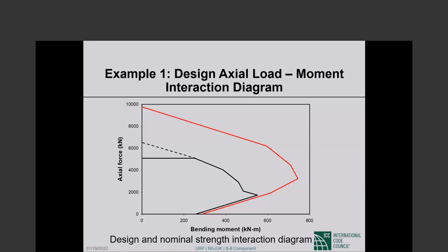What I want to say is that it is seldom that a spiral is compared with comparable circular ties. If you have a spiral with a pitch of 3 inches, I doubt that if somebody wants to do the same column with circular ties, he will use 3-inch spacing of the circular ties. That typically is not done.